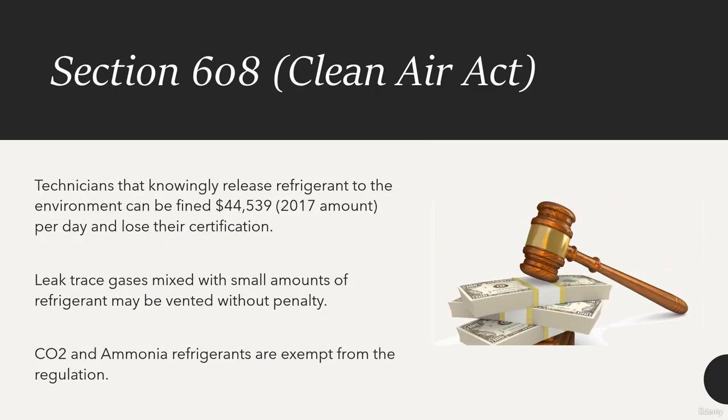Technicians that knowingly release refrigerant to the environment can be fined up to $44,539 per day and lose their certification. Leaked trace gases, as we mentioned earlier, mixed with small amounts of refrigerant can be vented without penalty. Natural refrigerants such as CO2 and ammonia are exempt from the regulation and can be vented.